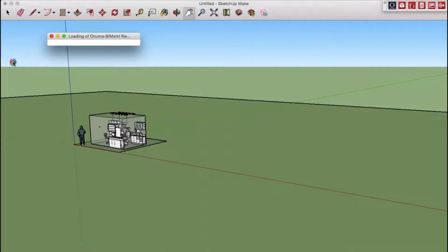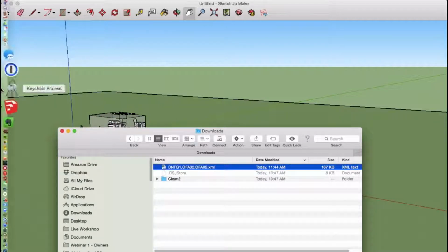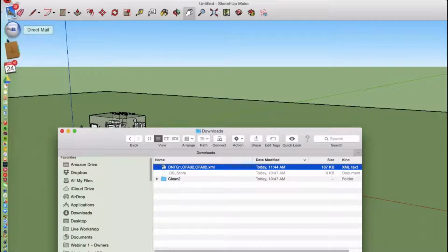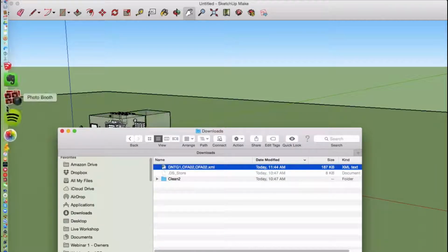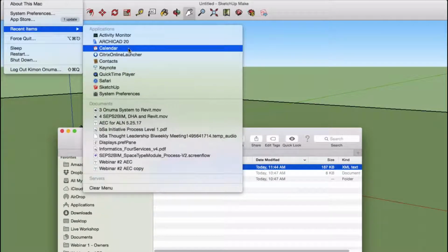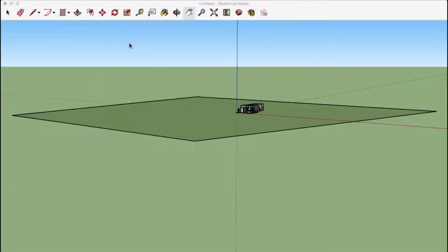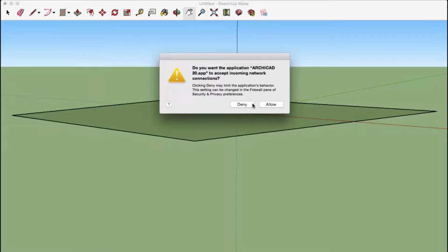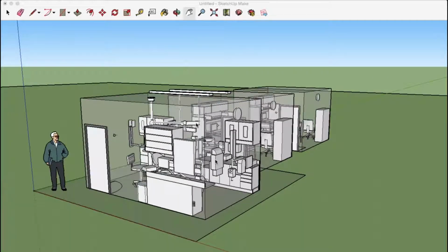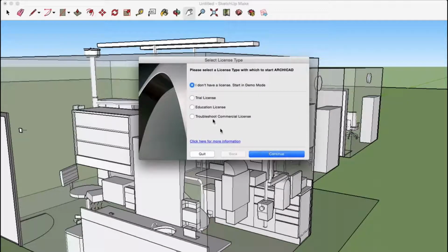available to be used. So let's see if my machine can handle all these models being open here, but I'm going to open up ArchiCAD because we promised we're going to go back to Revit again later. And this is an important point for our presentation: we're not stuck to any single application. Each application has its pluses and minuses. Obviously there's a lot of Revit users out there, a lot of SketchUp users, so there's the complete model in SketchUp. And if I clicked on these objects, it would actually give us the JSON names and the attributes that came along with it, and I can continue the design in SketchUp.